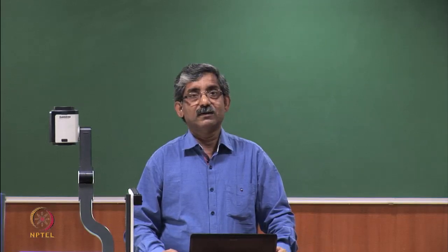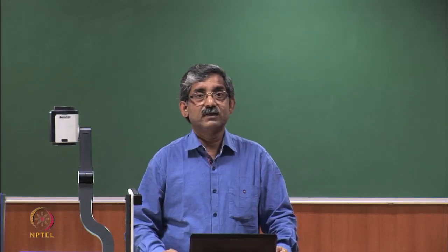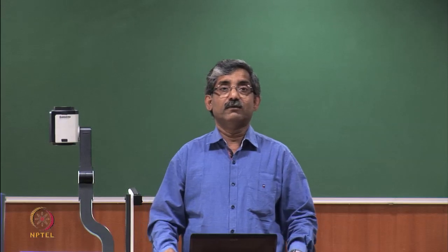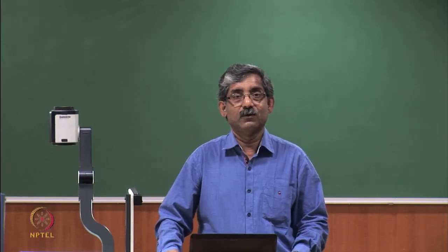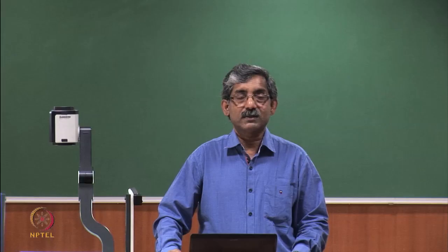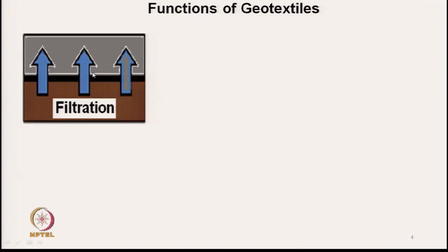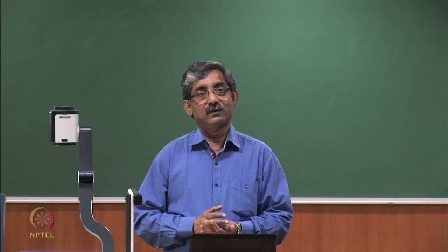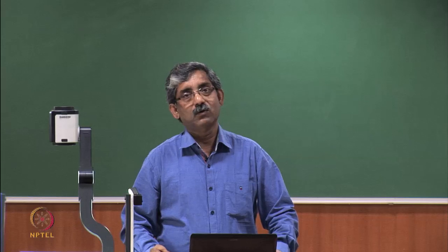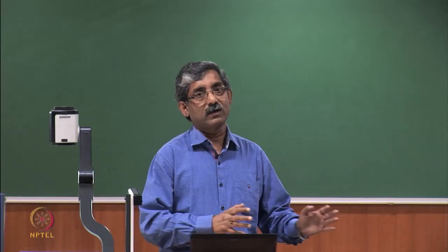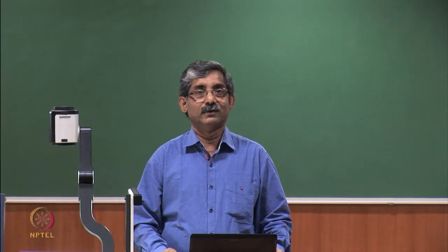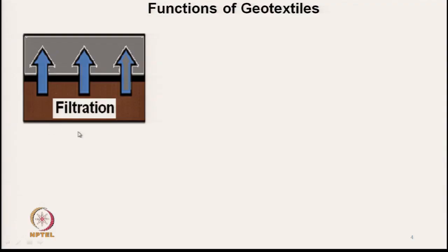First is the filtration, which is extremely important function, where the geotextile has to restrict the soil or sand particles, but at the same time it should allow the water to flow through. So, for that we need to understand the filtration behavior.